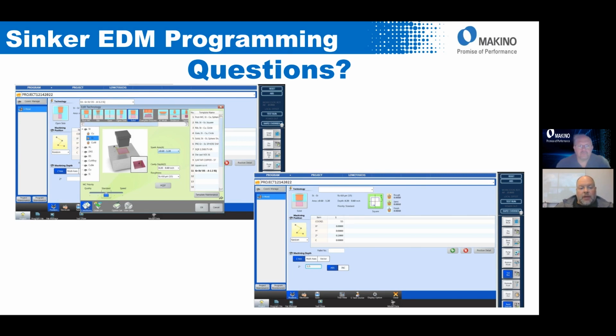And then as we go deeper, we start to pick up area, and then it gets more of what you technically programmed to. So then the machine is much more efficient. So the adaptive control is really the key in this case. If we go in on a pencil point and then we go up to a large area, it lets the machine make that adjustment in the background and adjust on the fly, and then go back to your program settings to run efficiently based off of the area you picked.